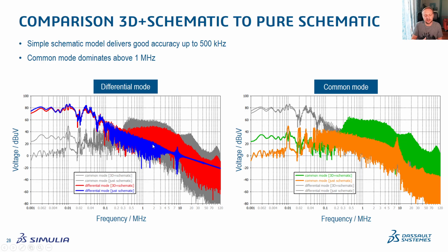But something like 10 or 20 megahertz is a very realistic value up to which such a circuit model with parasitics works well. Everything above, when you move towards 100 megahertz, you typically will not be able to build a good parasitic model for that, and then your S parameter description is the only way to work.